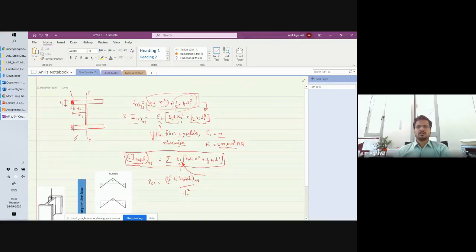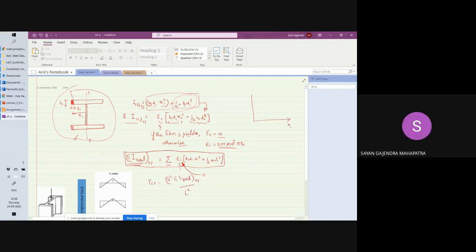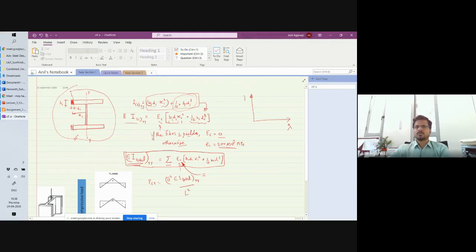Let's say the dimensions of the cross section, the overall dimensions of the beam, are known to you, right? So let's say I'm calculating the EI, or this curve, lambda versus capacity, the critical load, for the minor axis. Likewise, there will be a curve for major axis. This one will be minor axis. This is how it should look. And this will be my major axis.